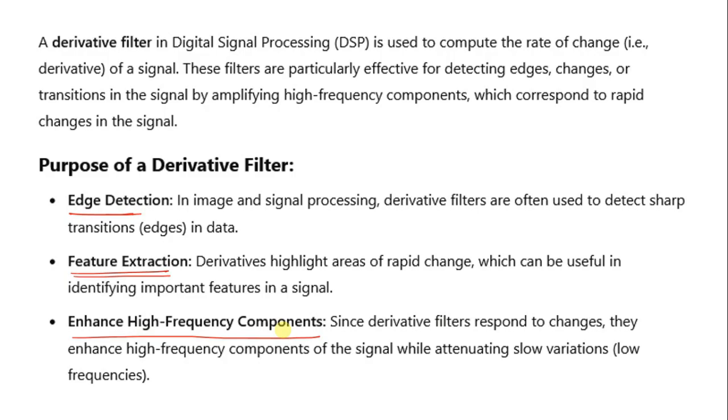If you take an image from here, what you will see is a constant signal amplitude level, and at this edge there would be either a drastic fall or a drastic increase in the intensity. So in a plain background, when there is a drastic increase or decrease in the amplitude levels, that is called an edge.